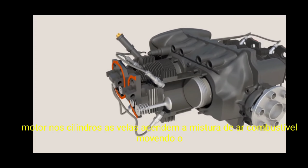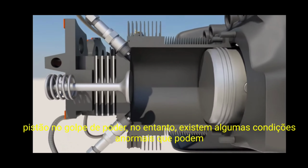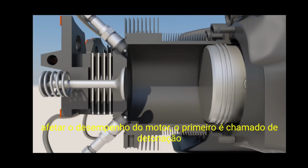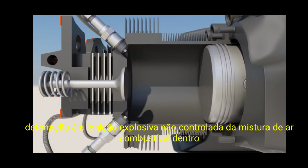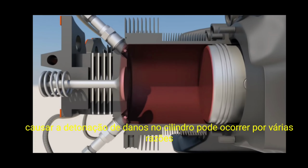In the cylinders, the spark plugs ignite the fuel-air mixture, moving the piston in the power stroke. However, there are a few abnormal conditions that can affect the performance of the engine. The first one is called detonation. Detonation is the uncontrolled explosive ignition of the fuel-air mixture inside of the cylinders. It results in high temperatures and pressures, which can cause cylinder damage.